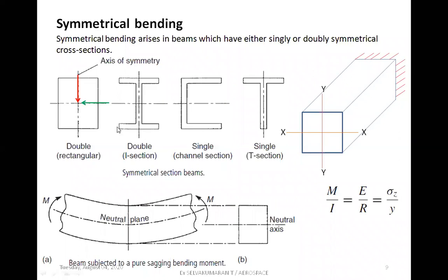Now for example, the load is acting upward. So now the load is acting upward, P into L, which is again the bending moment about the x-axis. So this causes compression of the top surface. Now I can call this moment a negative bending moment. And this yellow arrow mark pointing to the right-hand side, just transfer this load to your cantilever beam. If you try to bend like this, the surface is subjected to compression. So the resulting bending moment is negative.